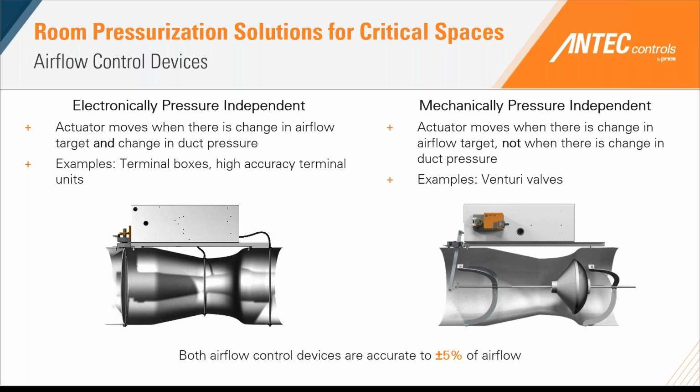Now, due to the nature of these critical spaces having such an impact on safety of the users in the space or potentially patients, we're going to want to ensure that we're introducing and utilizing air valves that can help control airflow accurately. So in this sense, the two approaches we have are utilizing an electronically pressure independent air valve or a mechanically pressure independent air valve.